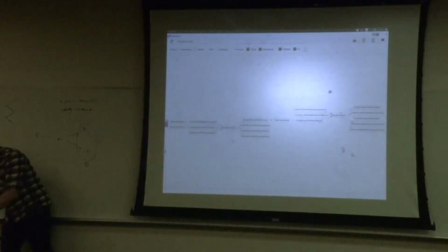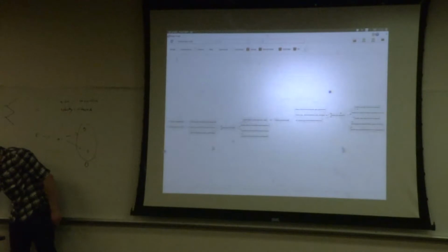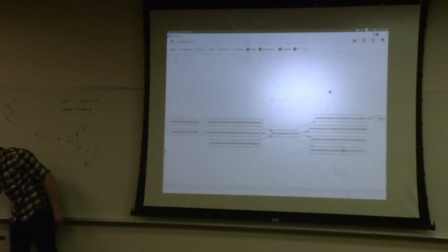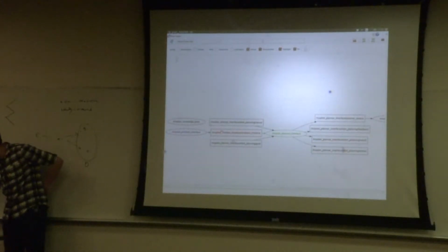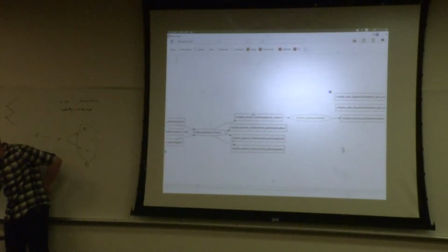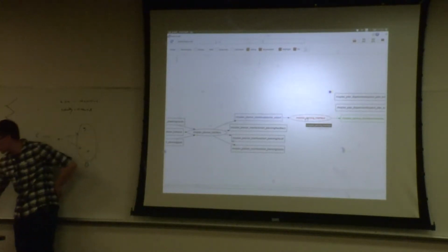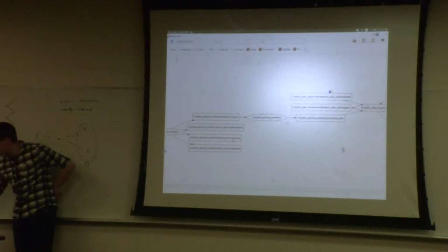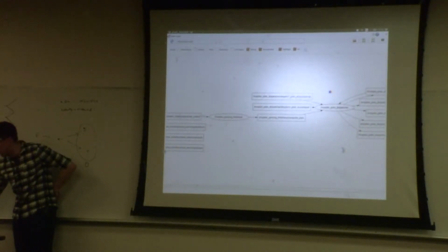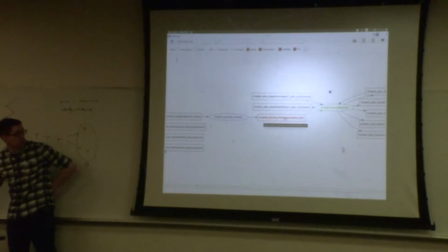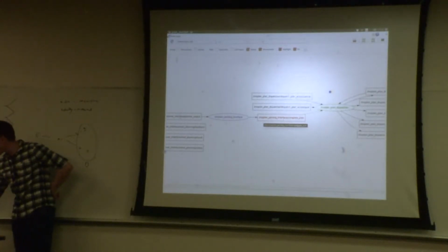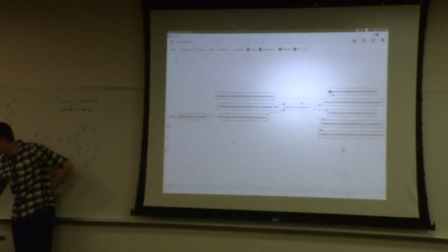And I really find that it's helpful to get this bird's eye view of what's going on. So as before, there's the problem interface publishing the problem instance, and it's being subscribed to by the planner interface. The planner output now has its own subscriber, set up again by parameter, this parsing interface. The parsing interface is taking this string output from this topic and publishing a message on this topic called complete plan. And we'll have a look at that in a moment to see what it looks like. And that's being subscribed to by the plan dispatcher.